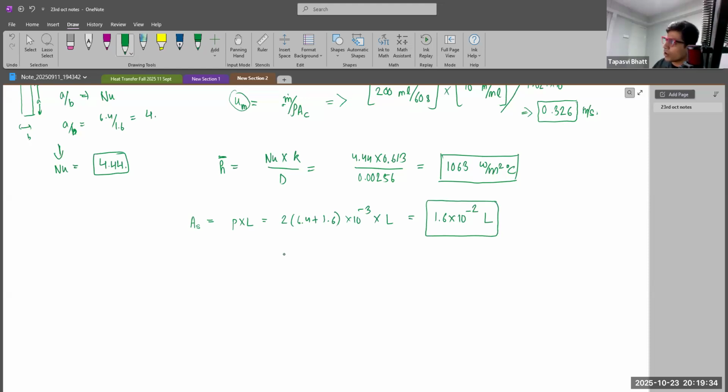Now, what is m dot? M dot is rho times AC times UM. What is AC? AC is the cross-sectional area, right? So density is 997 times 1.024 times 10 to the power minus 5 times 0.326, which is 3.328 times 10 to the power minus 3 kg per second.